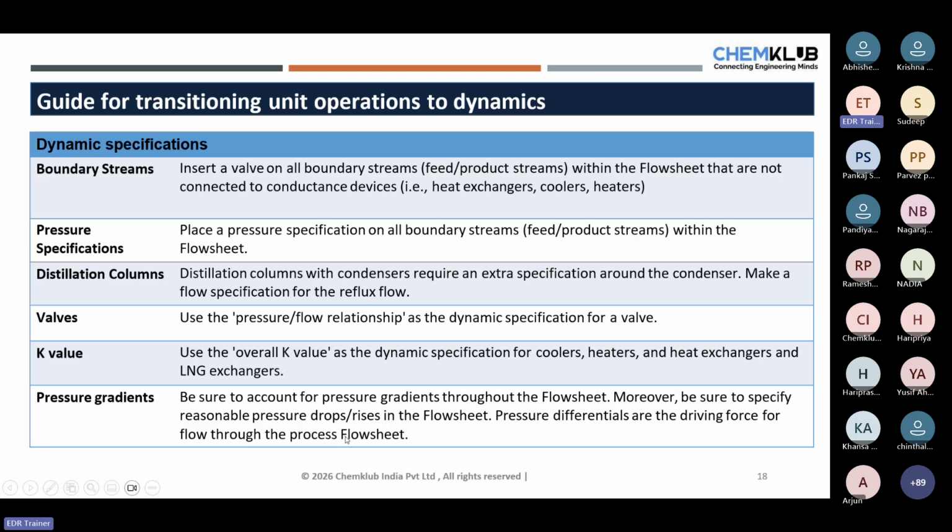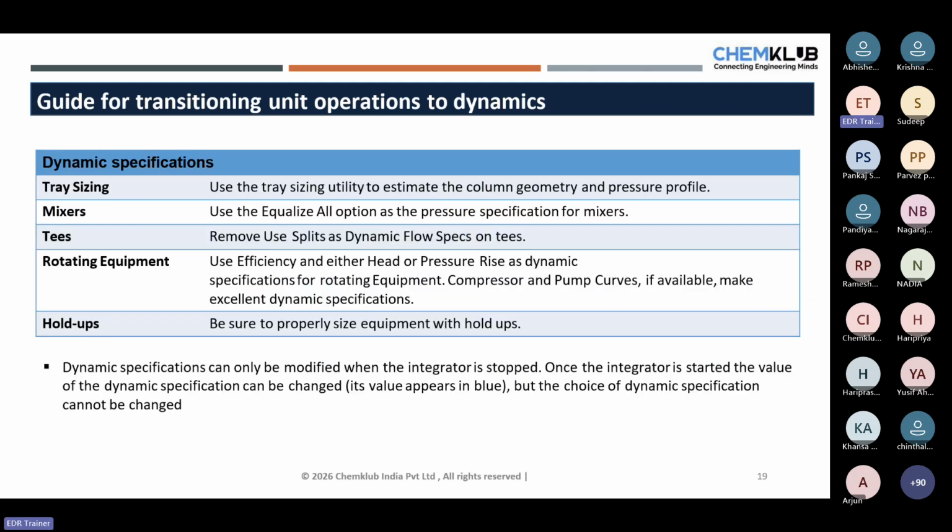The pressure gradient: be sure to account for pressure gradients throughout the flow sheet. Moreover, be sure to specify reasonable pressure drops or rises in the flow sheet. Pressure differentials are the driving force for the flow through the process equipment. So this is a very important concept that we have talked about many times.